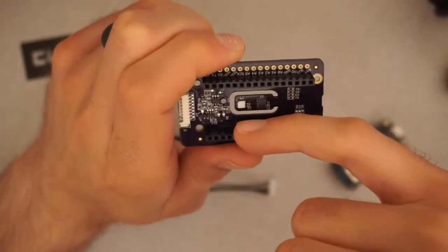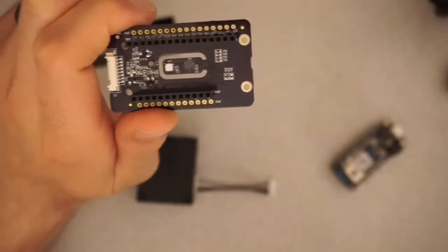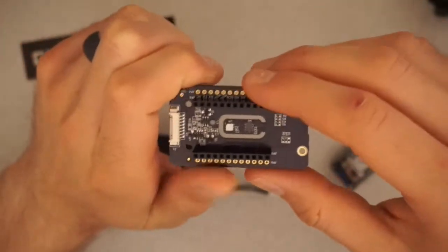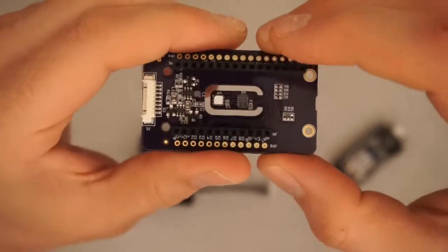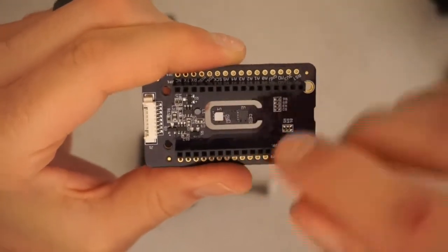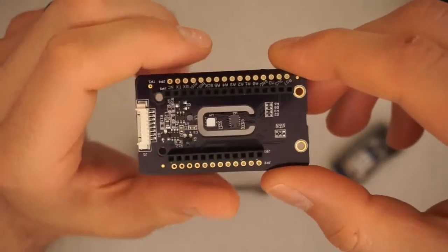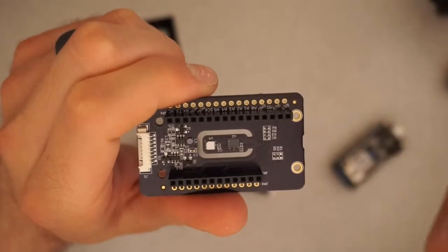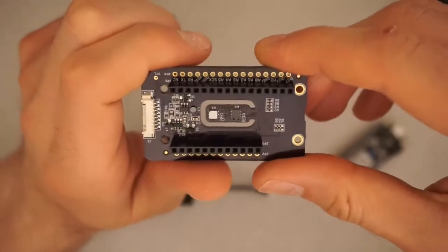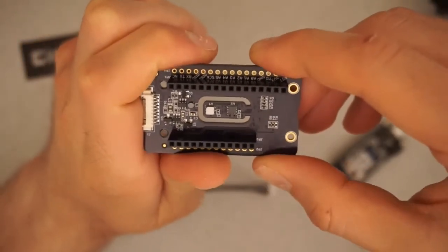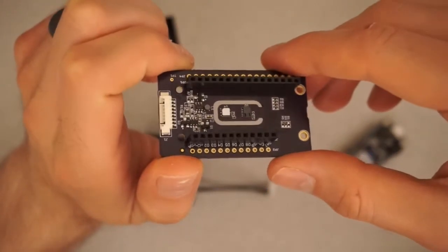The sensor right next to it, this guy is an SI7021. So it is a combination humidity and temperature sensor. This particular one, if you look carefully, it has a cover on it. So this cover comes with it from the factory. It'll protect the sensor from dust and other things that could potentially get in there. It still works just as well with it. So generally, the boards that I've built here all have that option.